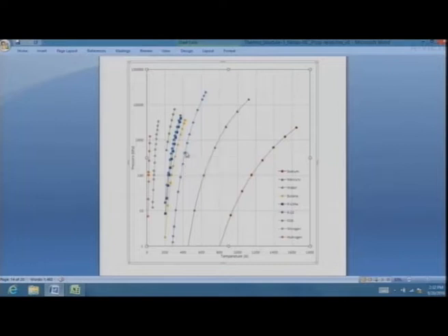Then you have this line here, which is for water. And to tell you that it's not just water and all these substances which behave like this, we have gone a little bit further ahead, and here these are the properties of mercury. We have seen mercury in the lab, which is a liquid. What it means is that at 1 bar pressure, mercury has a saturation pressure, a vapor pressure at that point, and some mercury vapor would be getting into the atmosphere, but this is very, very small.